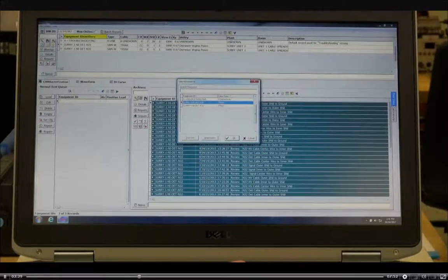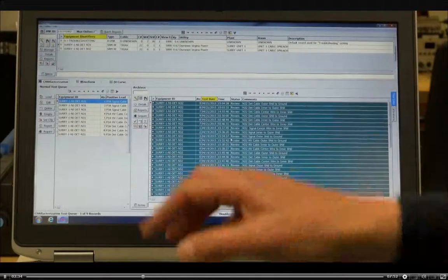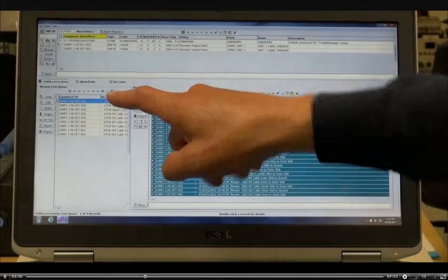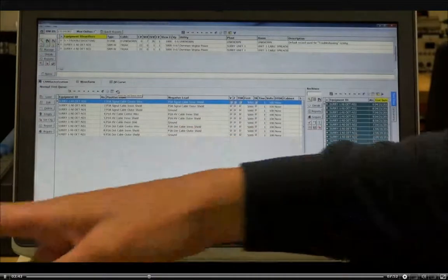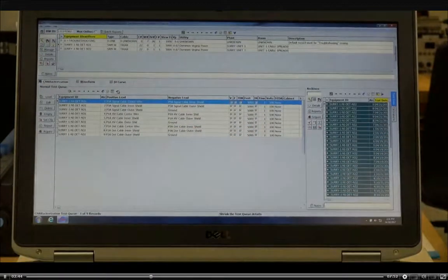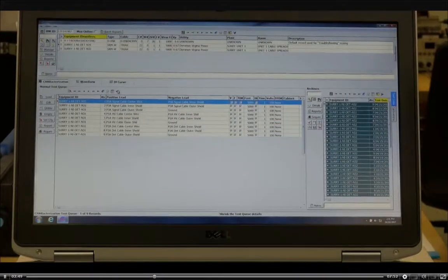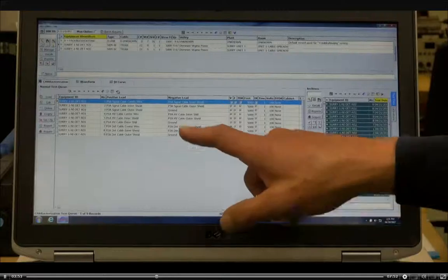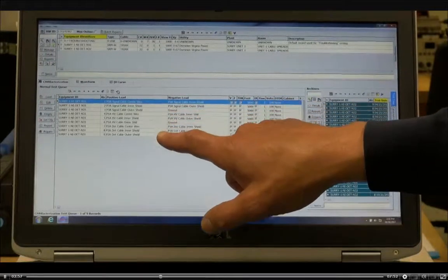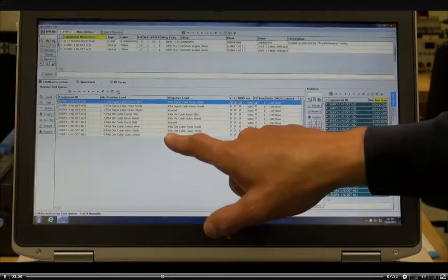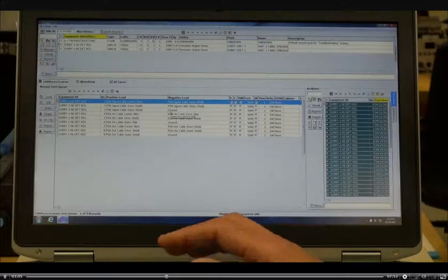There's N31. Hit OK. And that will load our test sequence 1 through 9 for what we're going to be testing. Little blue arrow right here, you can open this up and see a little bit better what we're talking about. Our procedure says we're going to be working to get P2 alpha, and then TDR data for center wire to inner shield and outer shield to ground. Alright, so you can see here we have 9 tests. 3 of them are on P3 alpha, P1 alpha, P2 alpha. So P2 alpha in this case is test 7, 8, and 9. So those are the tests we're working on.